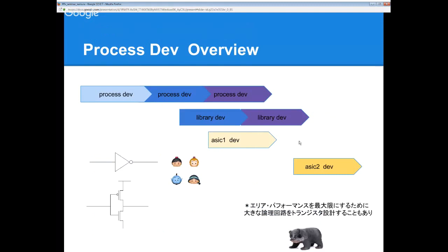So usually we do not do a transistor level design because we have a cell library. We just represent the RTL code, and the logic synthesizer compiles it into the netlist. The netlist has many cells and gates.